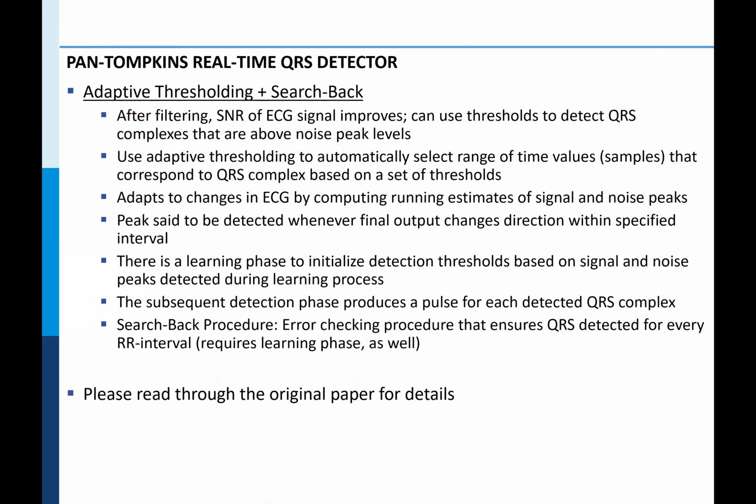Now, the final step with the Pan-Tompkins after the moving average, we talked about thresholding. Essentially, you can use a combination of adaptive thresholding and search back techniques to ensure that you have a very robust estimate of the direction of the QRS complexes. The adaptive thresholding is the way the original authors have recommended. It's just because this adaptive thresholding allows us to fit the variabilities that each and every human subject brings into the heart rate dynamics.